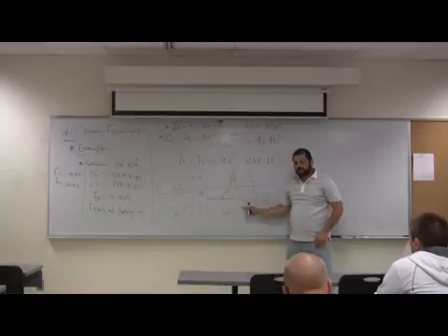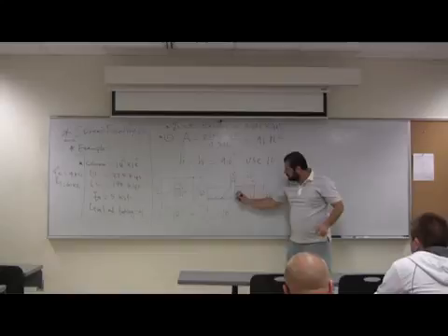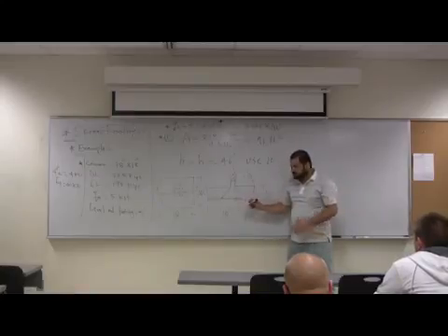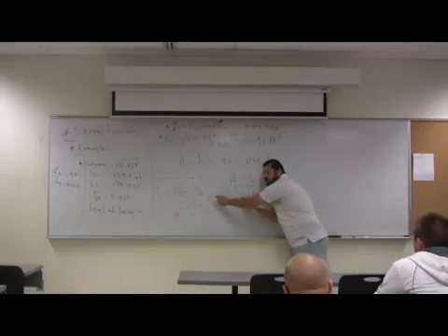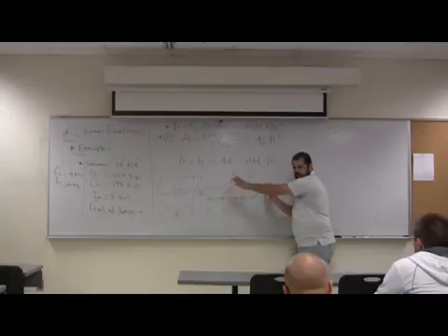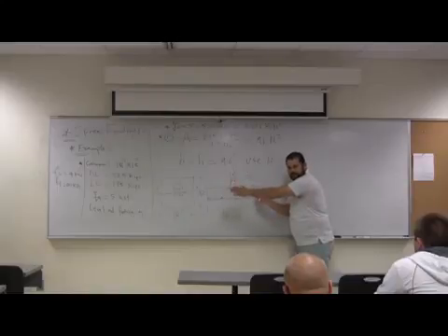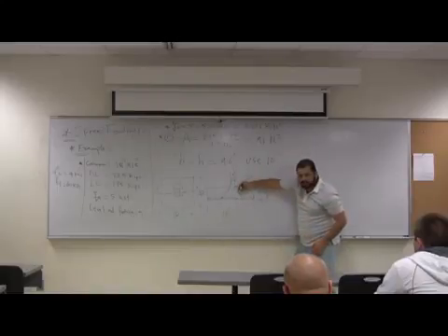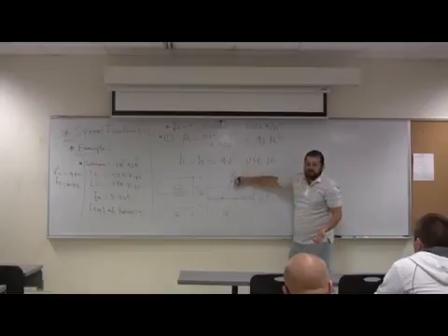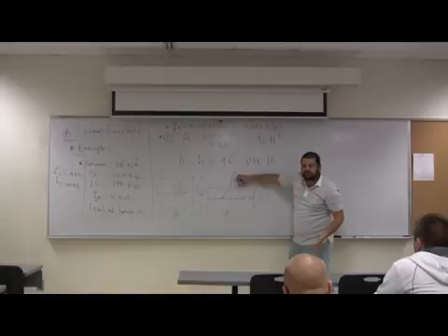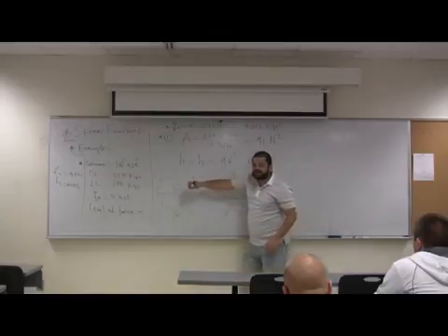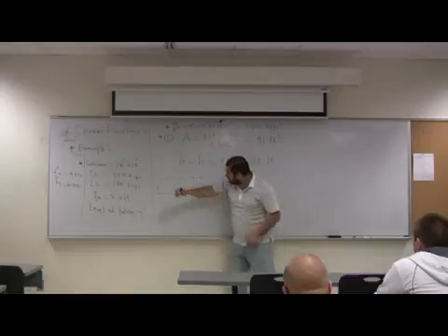They chop this piece such that the distance from here to here is D. So when this one is chopped and you measure it from the bottom, it's the column plus D on each side. But to the center, if you want to calculate the strength, the top is 0, right? So the distance from here to here is D over 2. So the critical section for that punching is all around. It's going to punch it all around.